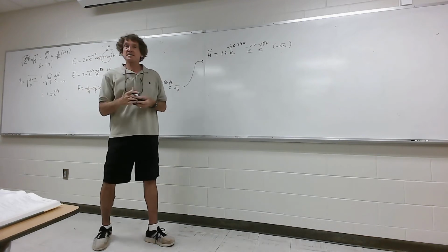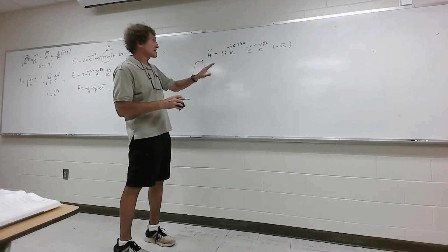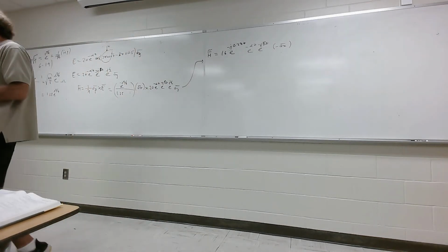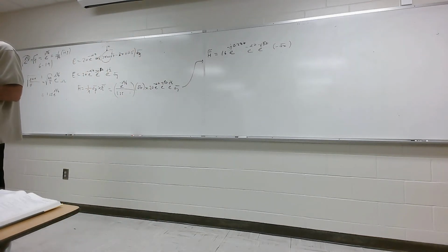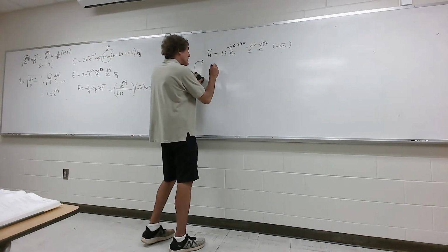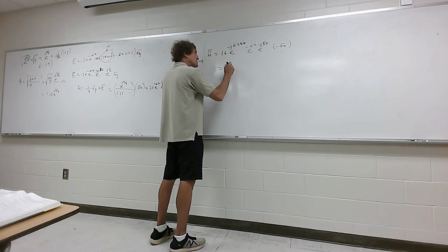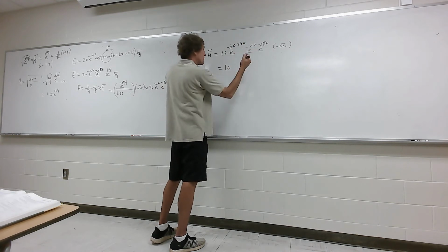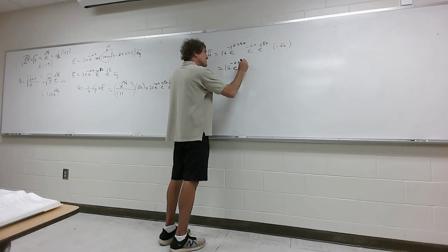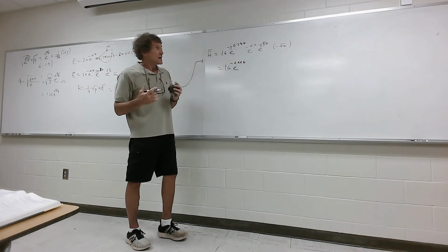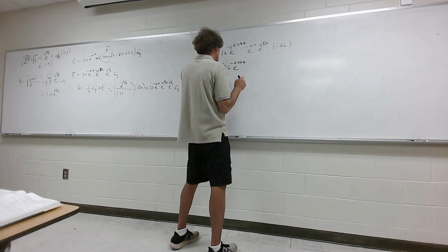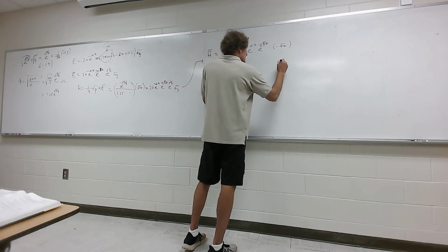So to get it back into the time domain, what do I do? Technically, I take this and I multiply it by e to the j omega t, right? And then I take the real part of that. But I know, and you know if you've been doing the problems, what I'm really going to do is simply bring that constant down. This alpha is strictly real, so it's e to the minus 4.44 z. That's all in front, right? Then I'll put the minus sign there, because that's minus ax. And I'll leave ax out here.